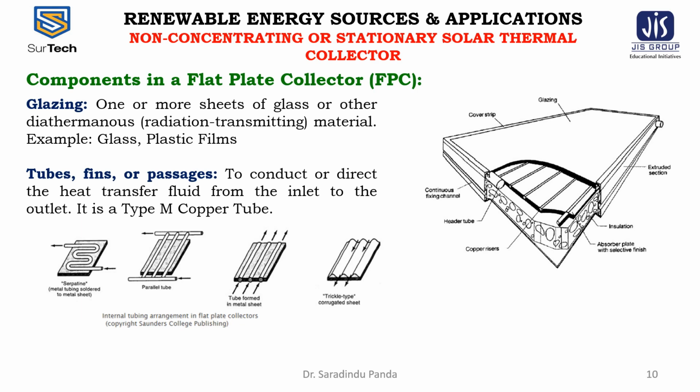The antifreeze mixtures can be used instead of pure water to alleviate the above said problems. The common antifreeze components are ethylene glycol or propylene glycol. Those chemicals are mixed with the water, and require closed loop systems and proper disposal due to the toxicity. Nominal antifreeze service life is about 5 years, after which it needs to be replaced.